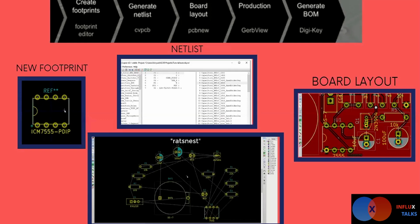Now, the next step is generating the netlist. What's a netlist? It's a simple file which tells us how a schematic and footprints are connected. Once you have the netlist, include it in your PCB layout. It may tell you that there are a few errors. Just go back to the schematic and footprints, clear the errors, and then get back.